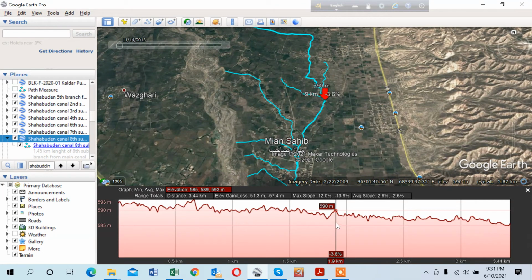In calculation you will find that the water level will be reducing rapidly, so you may not get the required water in any branch. That may occur because some branch channel outlets are a little bit higher than the other outlets. So you need some control structure in the main irrigation canal.